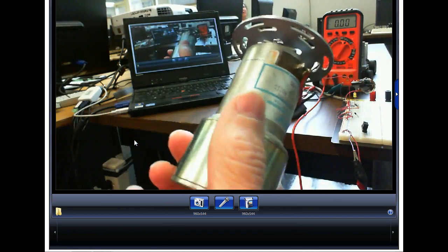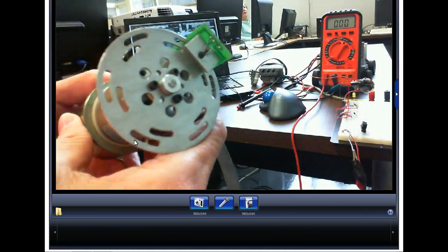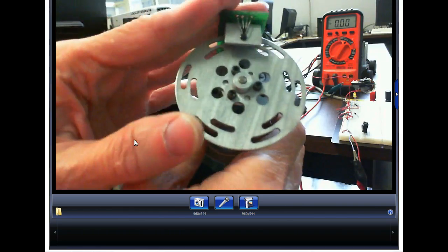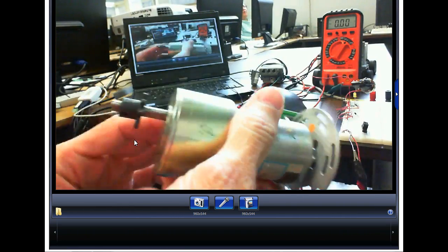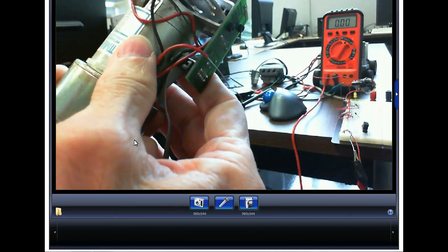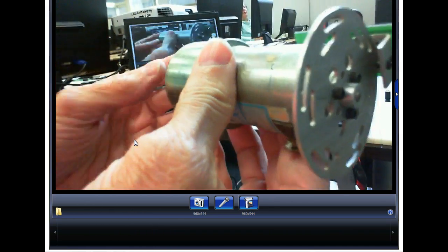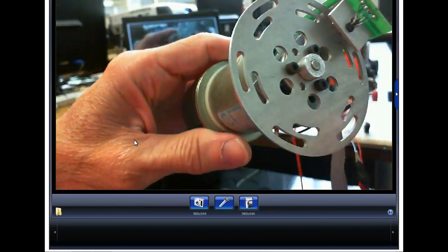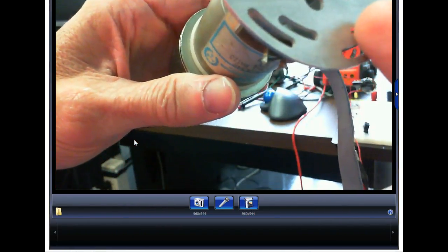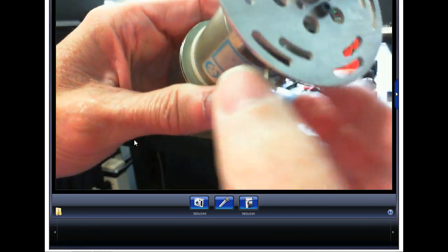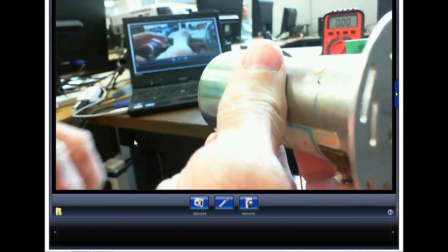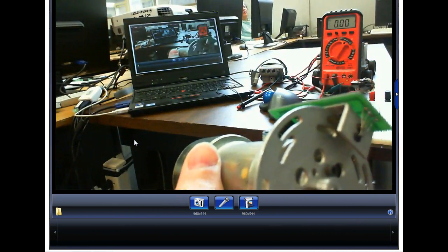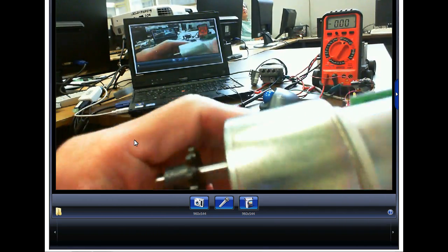So this is actually the servo motor off one of our robots. Now it looks like this has very poor resolution, but this goes through a 65.5 to 1 ratio. So it means for every 1 revolution down over here, this guy back here makes 65.5 revolutions. So you could take the number of slots and multiply it by 65.5, and that would be the resolution. Here's the actual gearbox right here. Y'all understand that? Which is pretty neat.